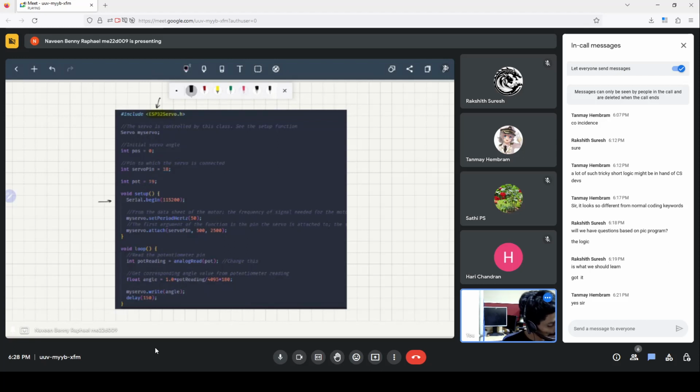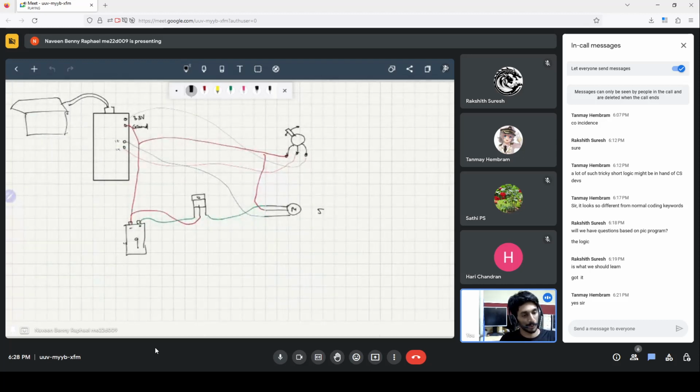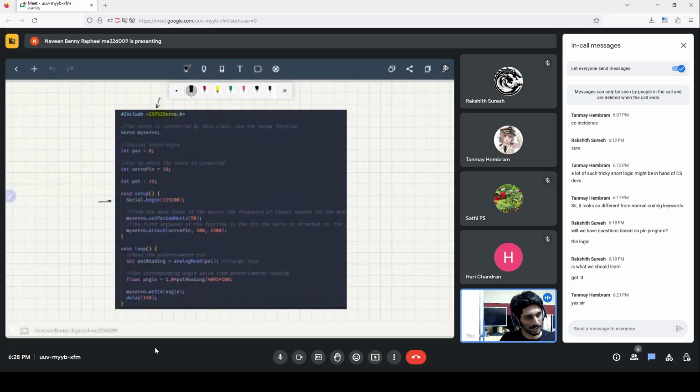Serial begin is a way that I can get the output of the ESP32 into the computer. This tells you the frequency of the input and things like that, and this is so that I can easily debug my mistakes. So in case the code is not working as I wanted it to work, I will insert serial dot println and then put the variable, let's say angle.